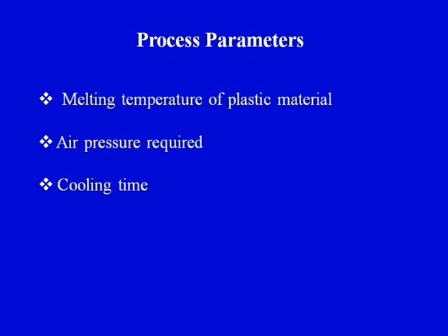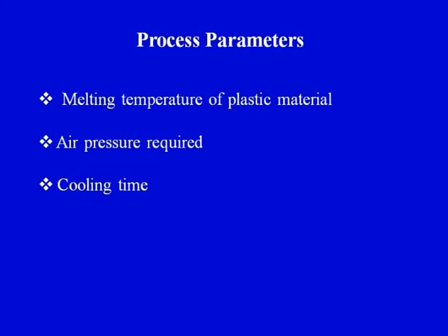Then second is the air pressure required, that is, how much air pressure is required so that we can inflate this parison to touch the mold walls. And finally the cooling time, the amount of time for which the two mold halves would remain closed for the final product to form, and when the two mold halves would open and the final product would be taken out. So this particular time is important.